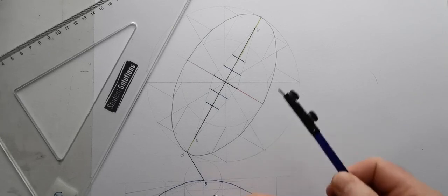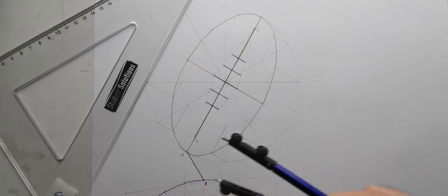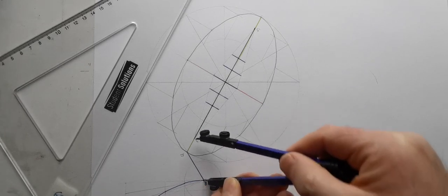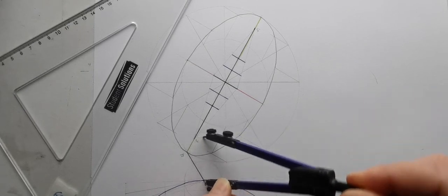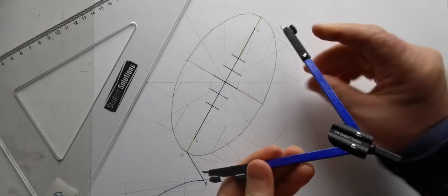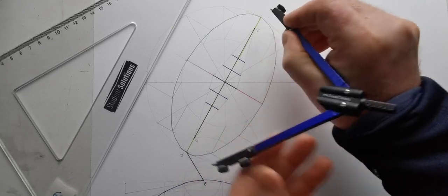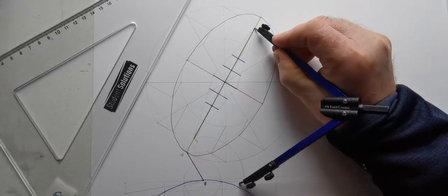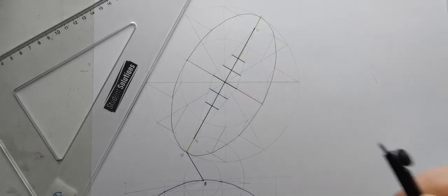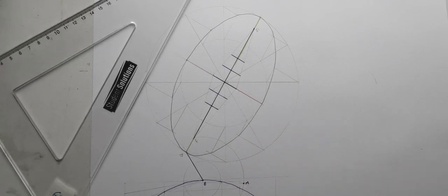So the formula is, wherever you're drawing the tangent from, draw an arc through the near focal point. So here's my arc through the near focal point. I want to swing the length of the major axis from the far away focal point. So that's from the far away focal point, and where they cross is here. I'm going to call it point M, and I'm also going to put this in green, I think.